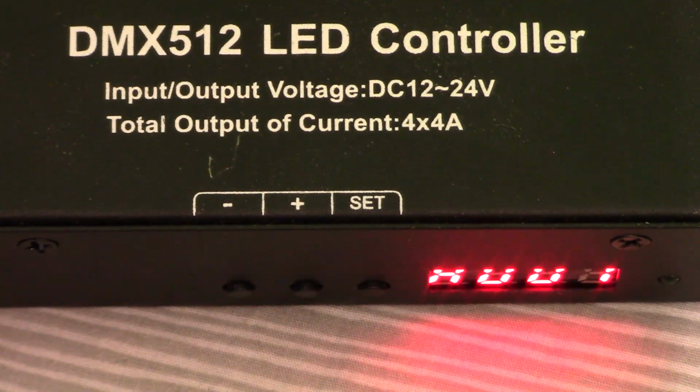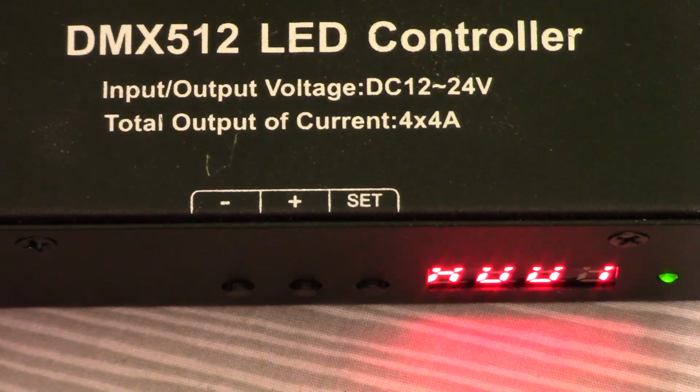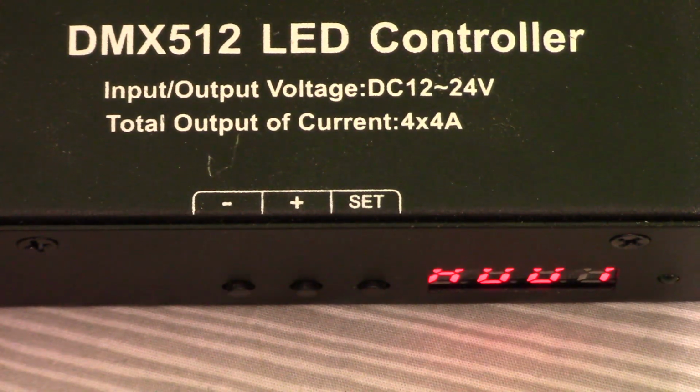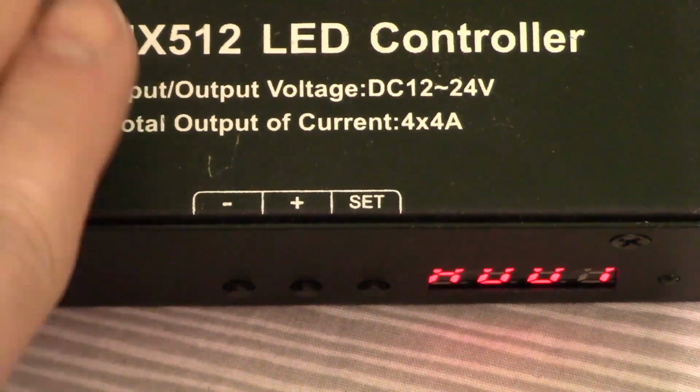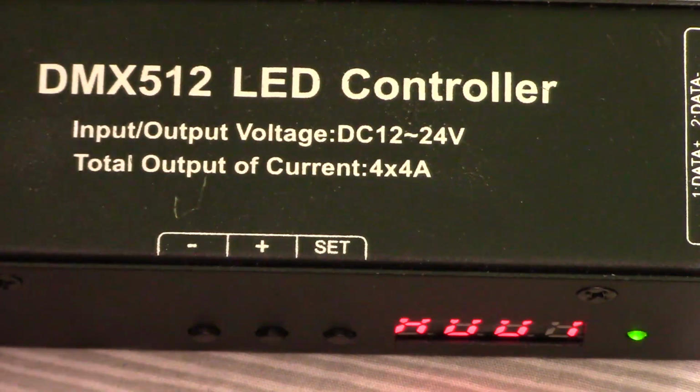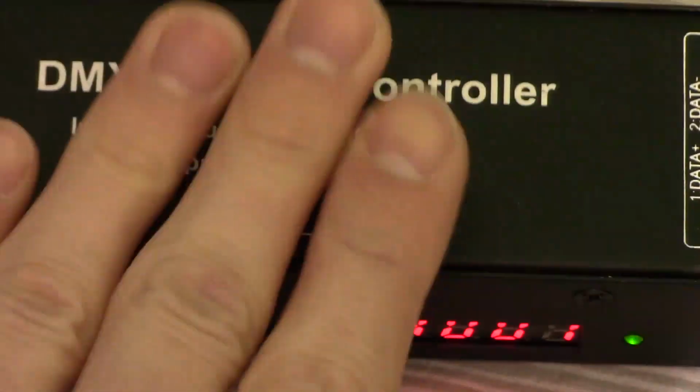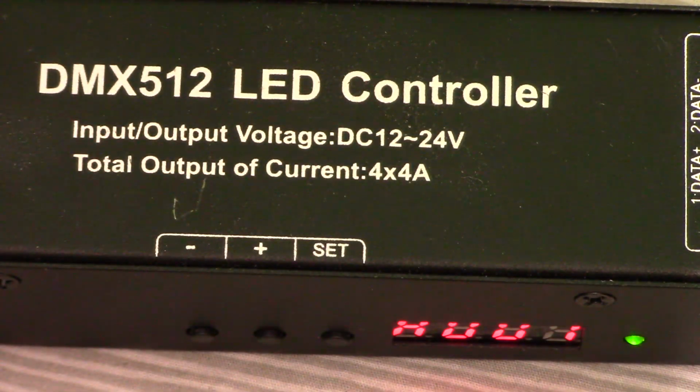And again, I said there are dimmers and different DMX decoders and receivers that have more than one channel. I've seen them with up to like 200 different channels for one box. But you can have 512 different devices on one system and 512 different controlled channels, and they can overlap. So if I wanted to hook another one of these up and have it respond to channel 1, it would still work.